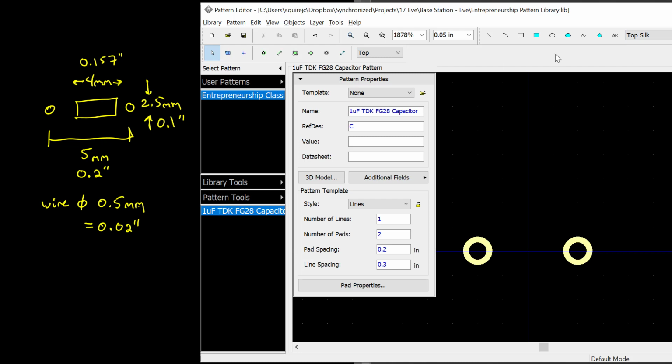There's a number of drawing tools you can use with a silk screen. You can draw rectangles. You can draw filled rectangles. That's filled with paint. That's filled with this silk screen, which is usually white paint. You can do circle outlines. You can do filled outlines. For all these choices, realize that this is just a silk screen. All you're doing is painting in non-conductive paint. For this case, we're going to want to use the unfilled rectangle.